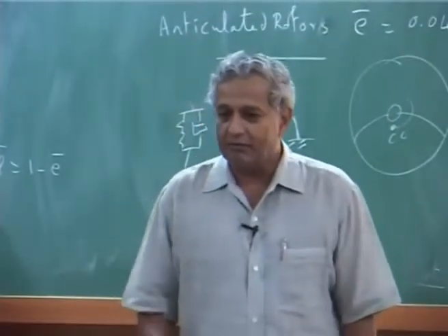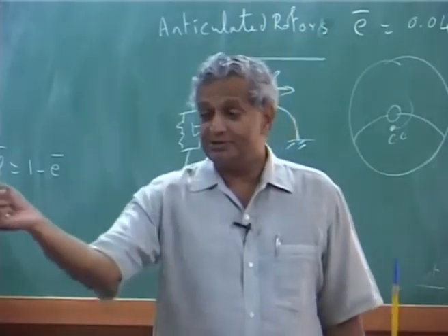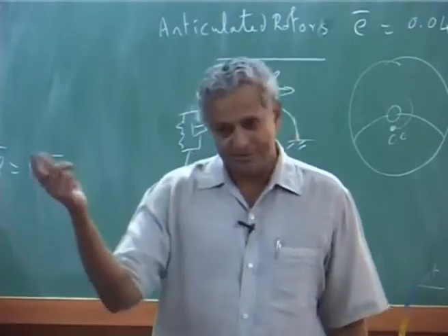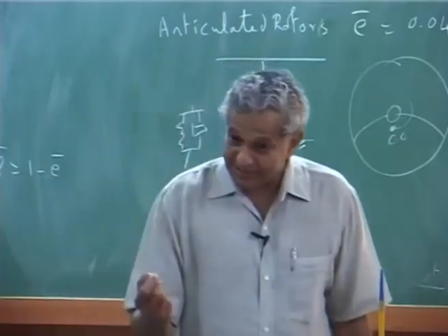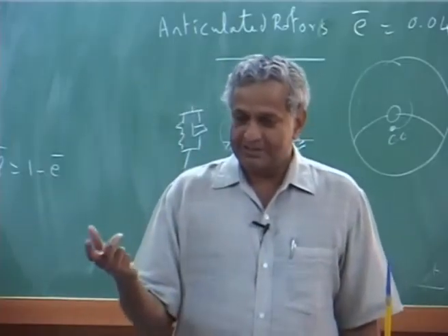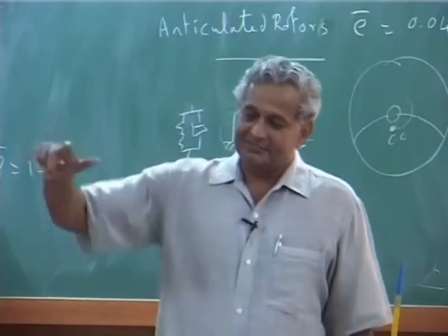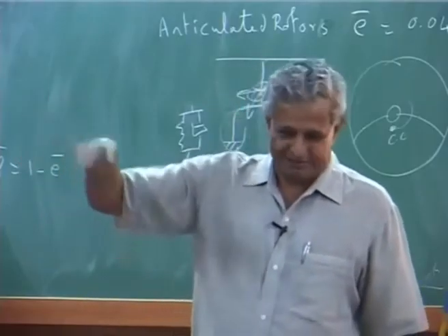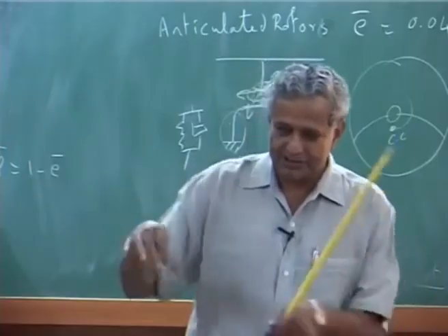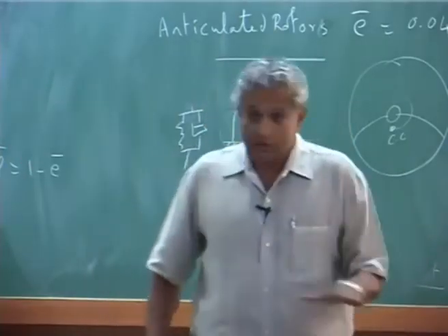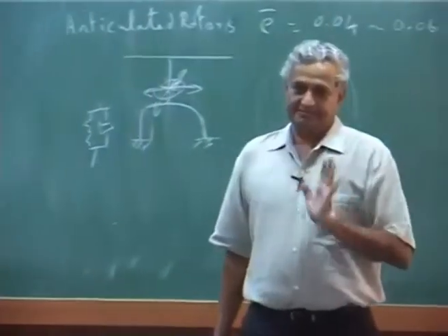But vicinity means how close? Even if it is 1.3 you may get in, 1.2 you may get, 0.9 you may get, but that will sometimes happen at a higher pitch angle, and you may not operate at that pitch angle. So, if you are at 0.7 you will not get into that instability.